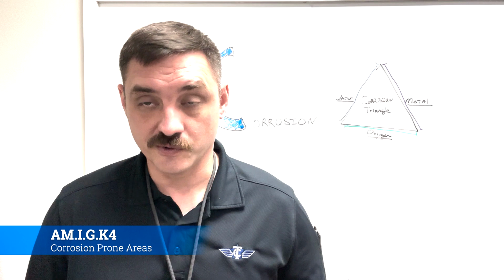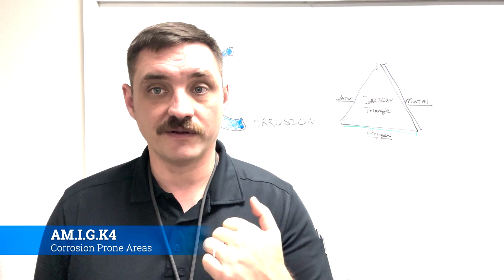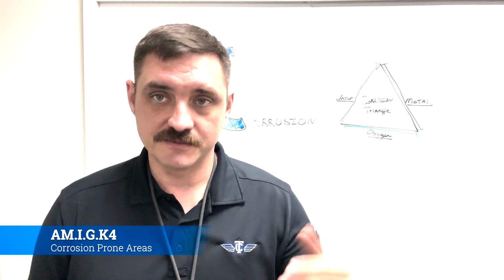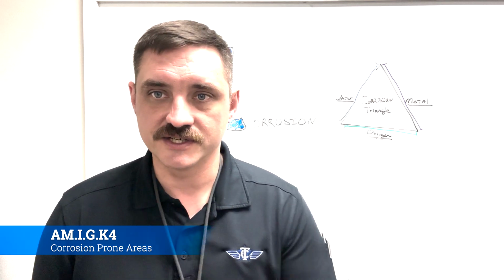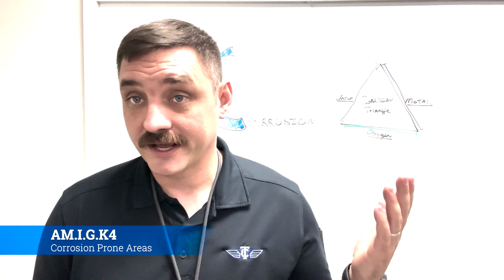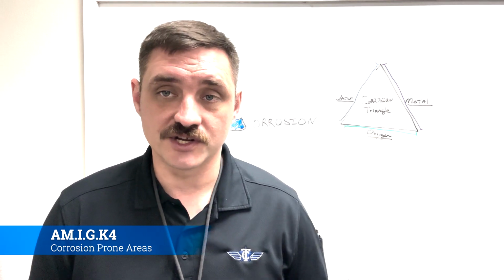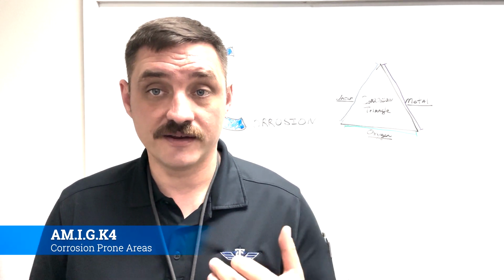Okay, engine frontal areas and air cooling vents. You'll see this too, especially on recip engines that fly around salt water. The cooling fins on the very front seem to corrode before the rest of the engine does. The reason, my guess, is that it catches a lot of the salt water first, and or the salty air first, and that's where it starts.